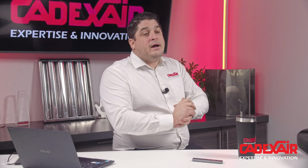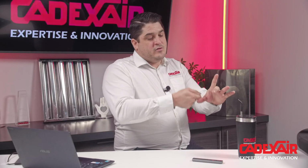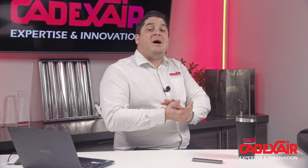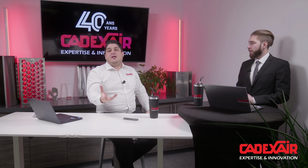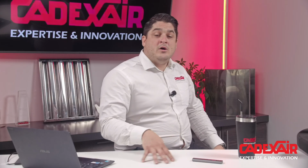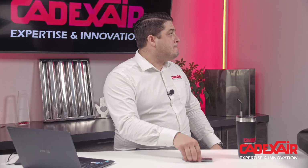I'm not a specialist in balancing. If you have a cartridge filter, because of the way it is built, you can use a wheel to take the speed inside of the filter. Or I know when you've got a baffle filter, they use what they call a Velgrid. It can take like 5 readings at the same time inside of the filter, and it can give an approximated face velocity of the filter. And I think they have a conversion factor that gives you the real airflow. So I think the Velgrid does a good job to make that happen.